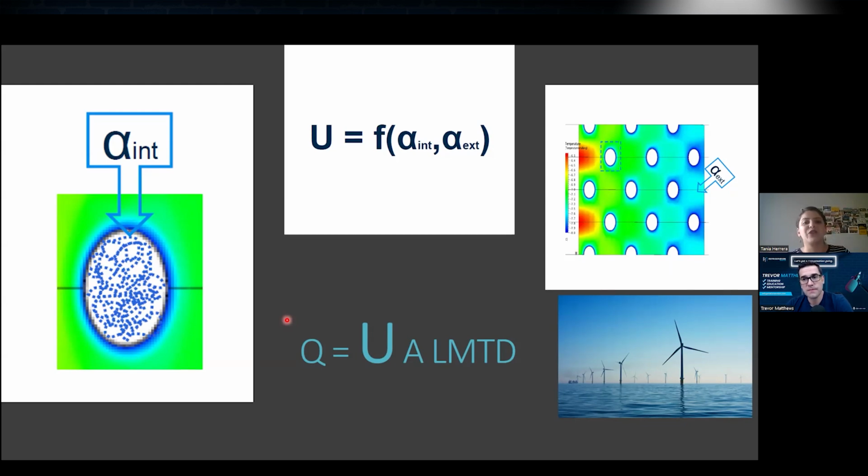So also it will be good to have high velocities in the air, good turbulence in the air, and we make sure to have this with our fins, because the fins are not just plain metal sheets. They have some corrugations that will increase the area and also increase the turbulence of the air while passing through the coil.